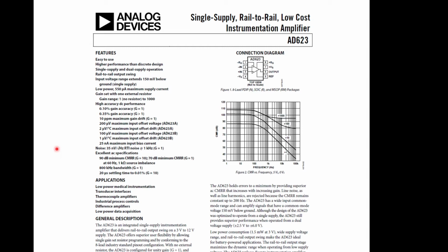So we can obviously build one from op amps, as we've looked at. We've looked at differential amplifiers with a single op amp. We've looked at differential amplifiers with 3 op amps, the so-called instrumentation amplifier. And we sort of hinted along there that if you want a really good one, you have to buy an integrated one. So here is a naive choice for our instrumentation amplifier.